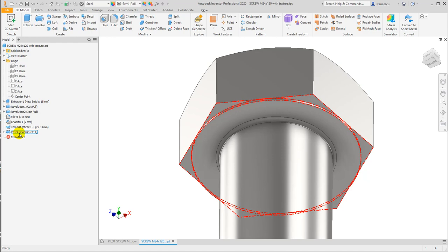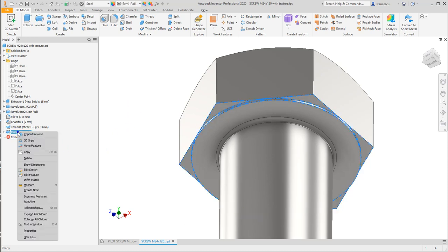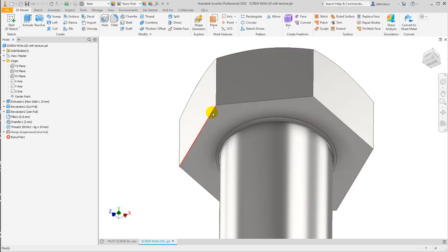This is the feature flange. We can change here the name with that name, flange. Why not? Good. And more than this, we can suppress this feature using this option, suppress feature. It disappears, and anytime we can unsuppress feature to have it back. This is very important and is new for this new tutorial. Every tutorial comes with new abilities.